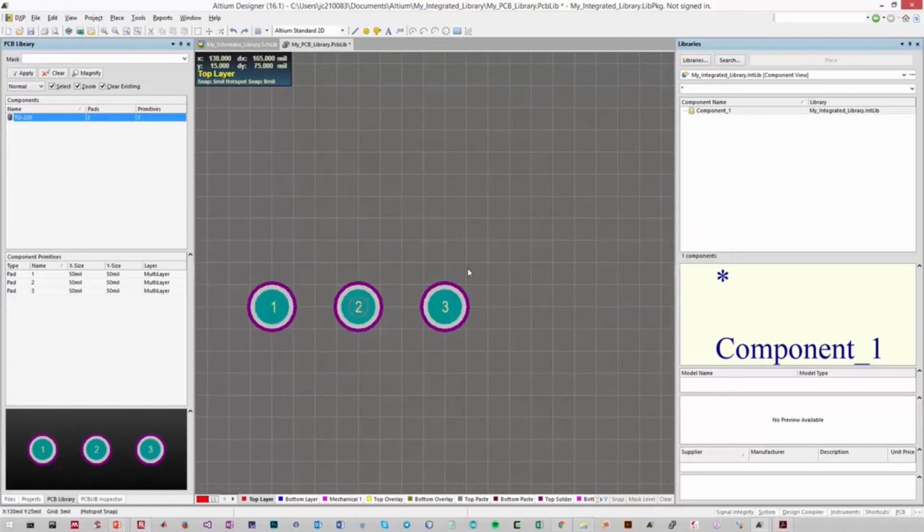So an often useful feature when you're designing your own component is to help people who are soldering your board by letting them know which pin is pin 1 for various components. There are several ways to do this. Sometimes you accomplish it by placing a small dot near the pin. A better way is to actually change it from having a circular hole to a square hole, because they can be easily milled as well.